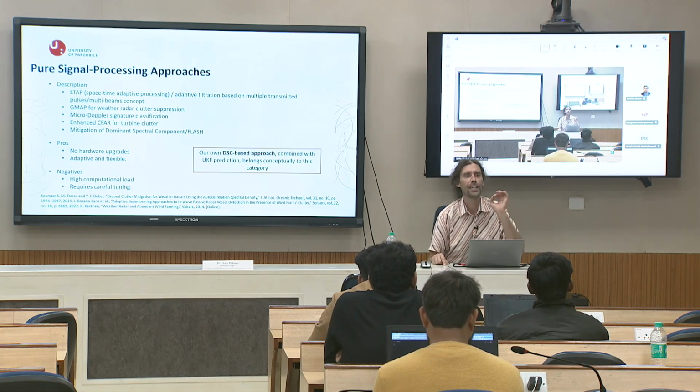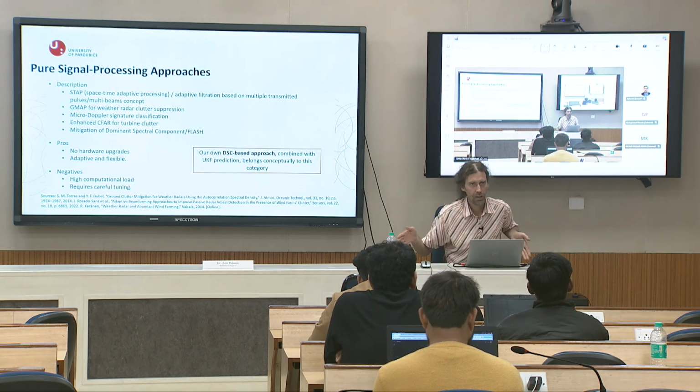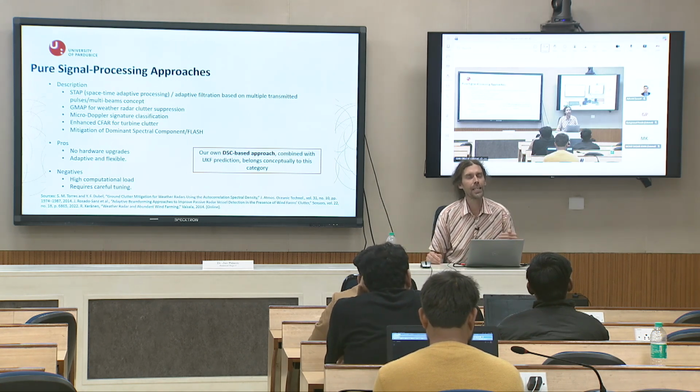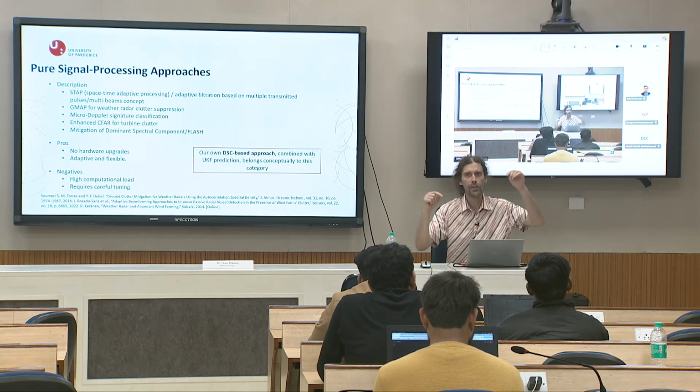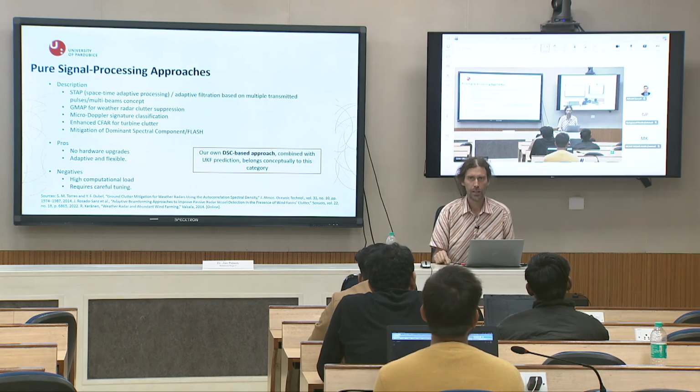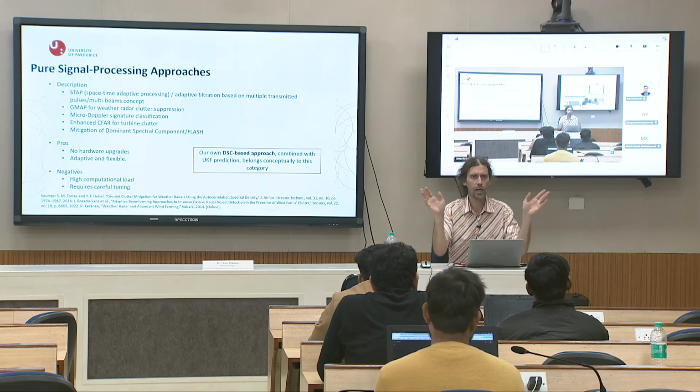So generally our approach is that we find these 3 worst harmonic components, meaning those with the highest Doppler shift. We investigate where their position will be in the next sample, and then we design a filter and mitigate just these 3 points. And you can ask me, okay, what about the rest?